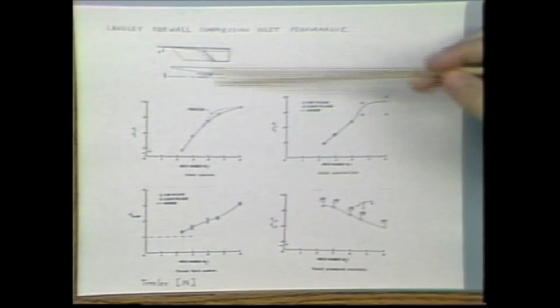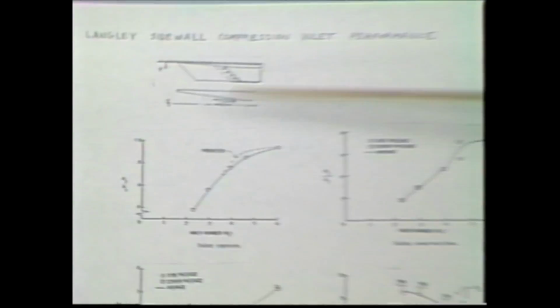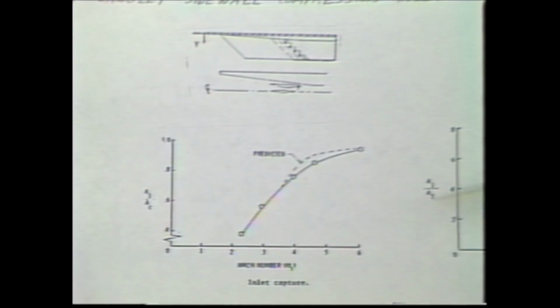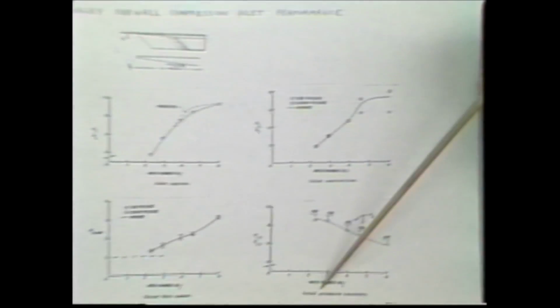Here is shown for a Langley inlet concept some of the performance parameters like inlet capture and inlet contraction ratio, throat Mach number, and total pressure recovery as a function of Mach number, just to give you an idea of how that kind of an inlet performs.